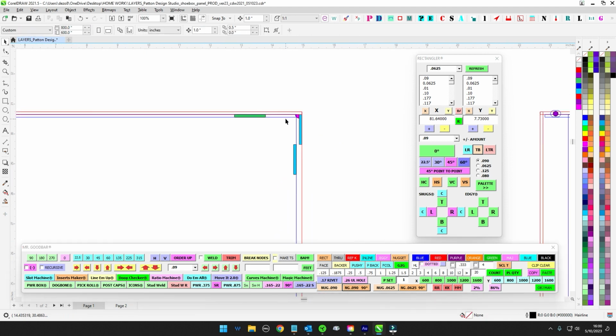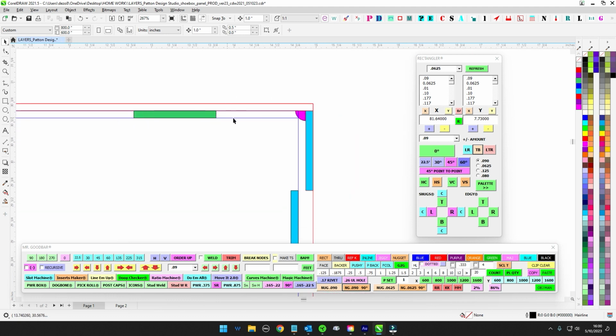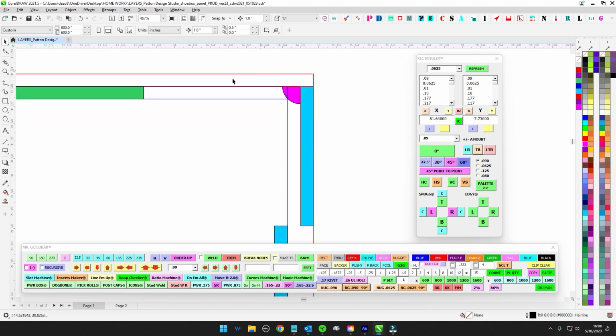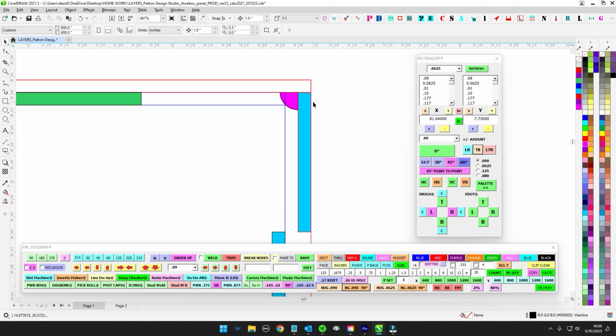And what we're doing is we're mitering this corner. So essentially now the backer is going to go to this nugget, and it's going to go across here, and then it's going to continue here. And what we're going to do is chop this corner off and dog ear it basically, so that way we have plenty of clearance for weld.